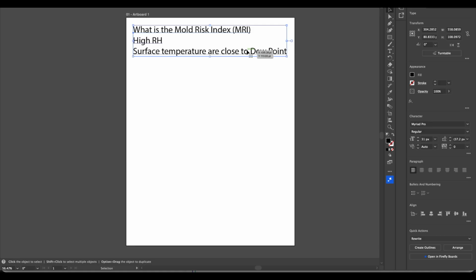But in a data center, the same conditions that are conducive to mold growth are also applicable to something called creep corrosion. So creep corrosion occurs when you have the same kind of conditions and you get condensation forming on some of your PCBs, for example, and it can cause corrosion of the electronic connections, the copper traces on the boards and so on.